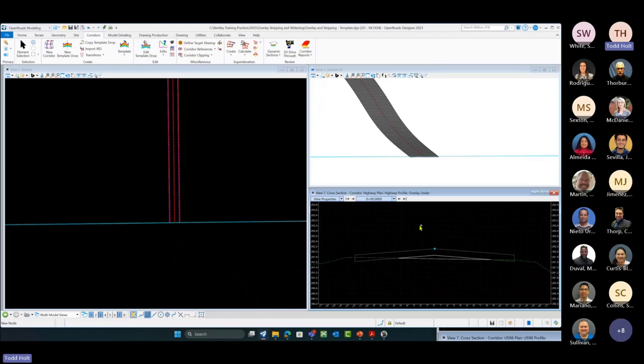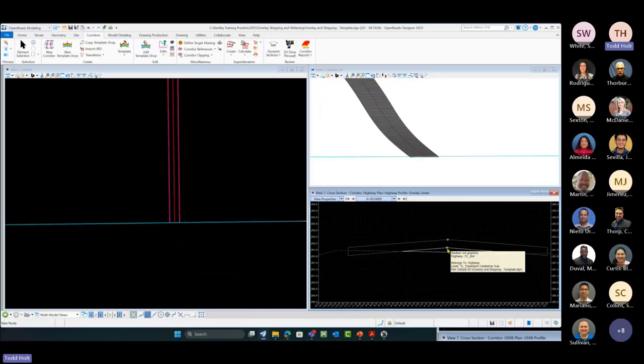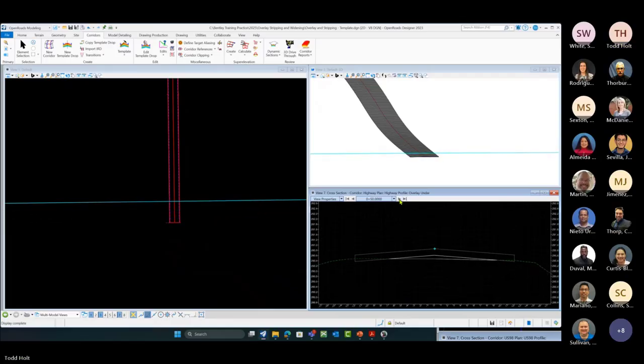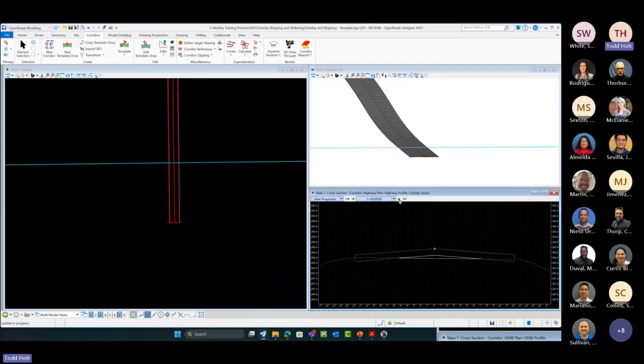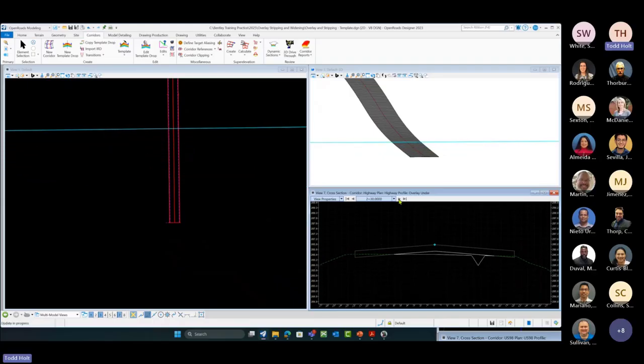So there, right, if we were coming back up to match this pavement design, so there's our new pavement, there's our existing ground, there's our overlay component. So we'd have to overlay up to the bottom of that surface. We'd also have some milling in there. But as we walk through our cross sections, right, we're going to see that milling component.